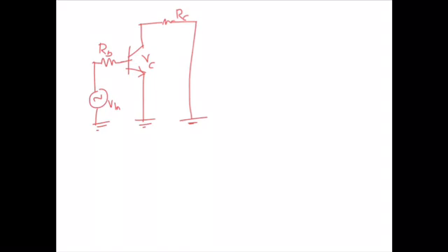Okay, in this circuit, as we can see, this AC equivalent circuit is represented by making the DC bias sources equal to 0. It means I am getting this circuit by making the DC bias sources VBB equal to 0 and VCC equal to 0. Whenever I talk about AC values, they are usually represented with the suffix in small letters. If I write the base resistance, capital R with a small b represents the base resistance of the AC equivalent circuit.